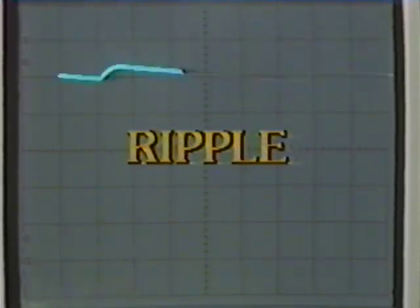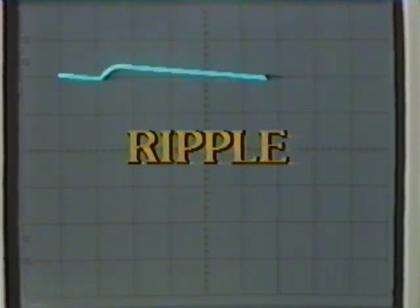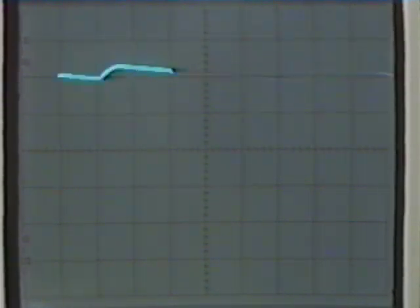Ripple is generally unacceptable because it may be superimposed on the signal as noise, and because it lowers the average DC voltage output. It should be noted that if the load remains relatively constant, filter components can be selected to provide the needed DC output.